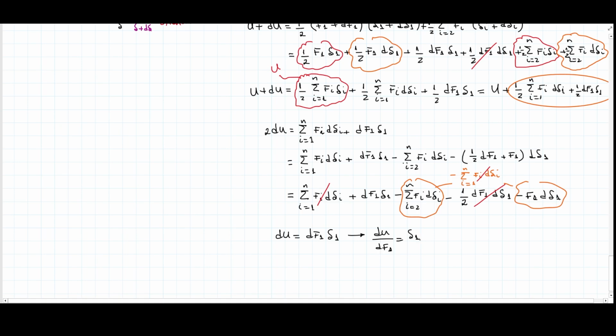So we have a relationship between the energy and, let's call it, deformation. What all this represents is that the partial derivative of strain energy with respect to this force here gives the deflection of the body in the direction of that load. Meaning, if I get such relations where I know the increase in the total strain energy of the system, and I know how much the increase in the force was, then I get to know the deflection at that point where the force was incremented. We can do that for any other loads, and it's going to say the same.